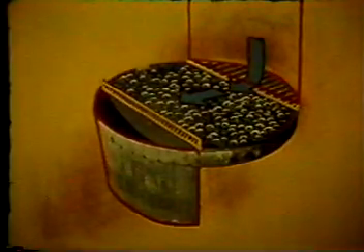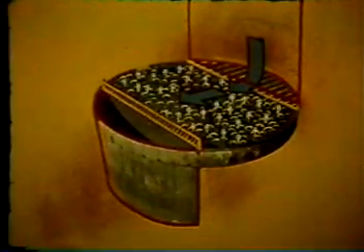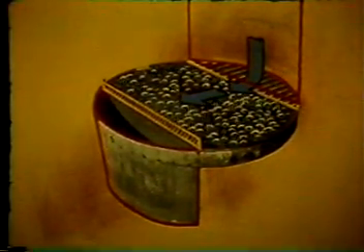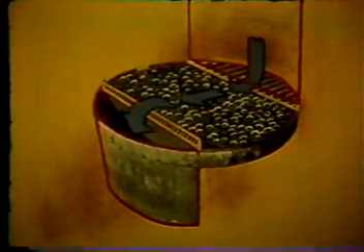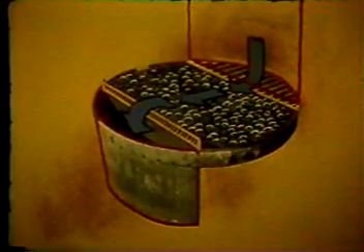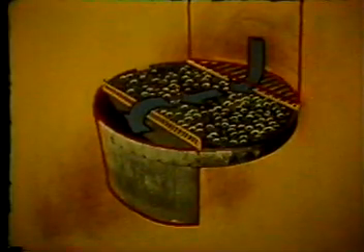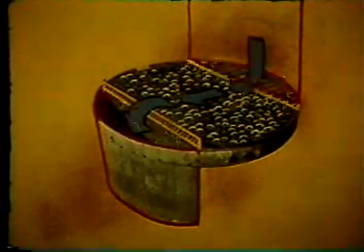Here the liquid comes in contact with the vapor ascending through the tray. The outlet weir serves primarily to maintain a liquid level on the tray, as well as to provide a seal for the downcomer. Trays with downcomers may be designed to have a single path for the liquid, or they may have two or more paths if the liquid rate is much higher.